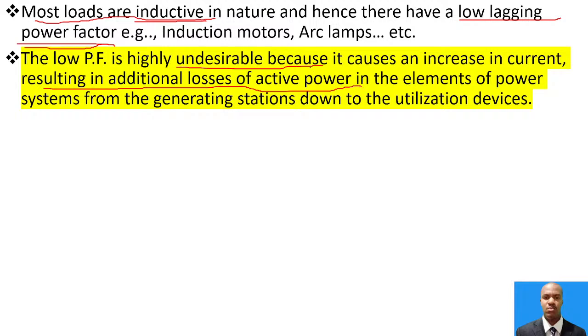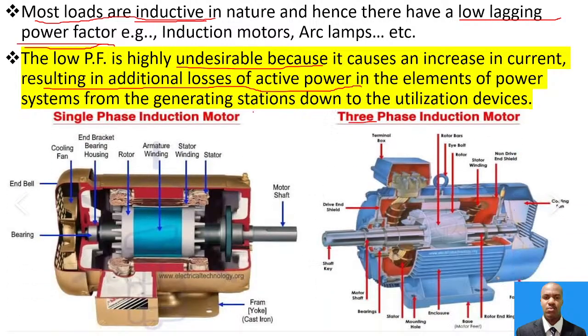Once you have a very low power factor, you have to operate your loads at a very high current, and this means you will incur high power losses in the elements of power systems, from the generating station down to the utilization devices.